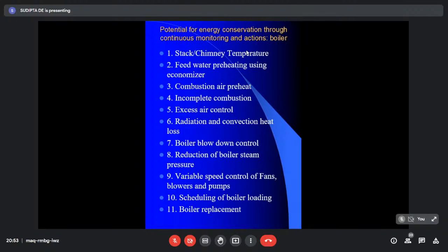In addition to that, in some of the coal varieties, there will be some sulfur as an additional combustible component. Depending on the coal composition, these three constituents can vary. But incomplete combustion means you are not burning these combustible substances fully. So what is happening? The heat release is less. So obviously your available heat for conversion of water to steam is also less.